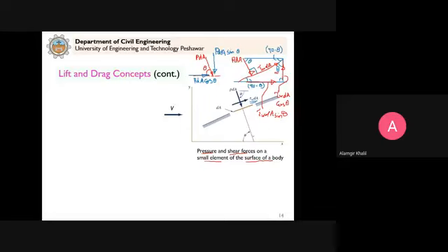So now I need to simply calculate what the components are in x direction. Because it is a differential element, dFx will be equal to P dA cos of theta. You can see here this component, P dA cos of theta in x direction.